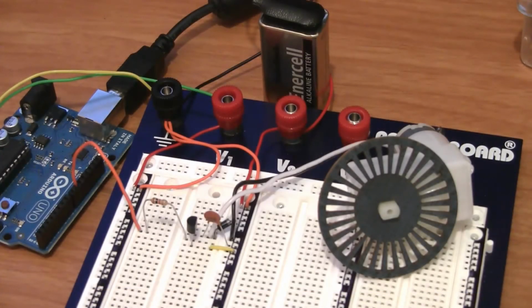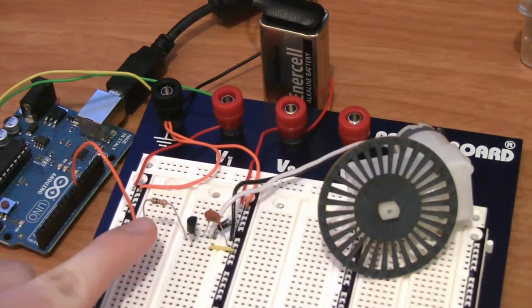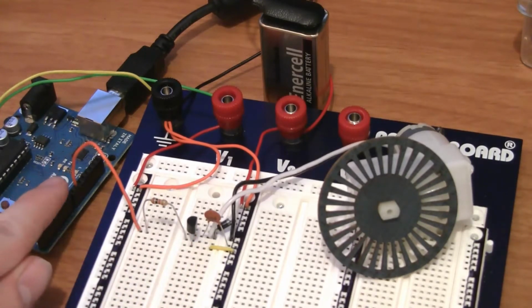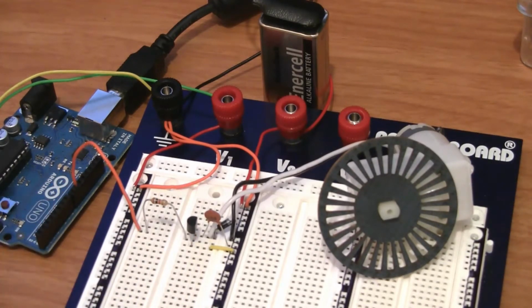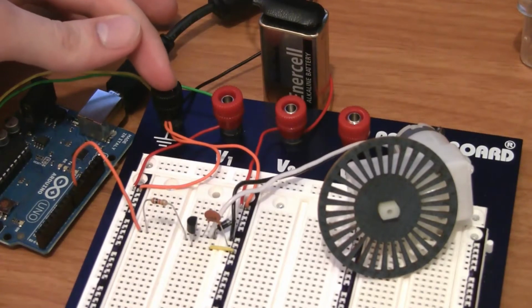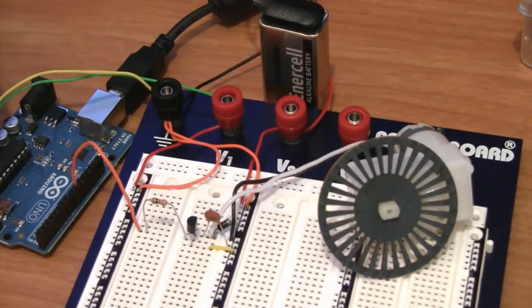Here's the circuit all wired up. Let's take note of a few important things. Here you can see the transistor, the capacitor, and the diode that I talked about earlier that will be controlling the motor. This is the 1K resistor that connects between the base of the transistor and pin 9 of the Arduino. The most important thing to note here, though, is that you always connect all the grounds between all of your voltages. I've used this binding post right here to connect the ground from the 9 volt battery to the ground from the 5 volt signal of the Arduino. This is to ensure that everything is operating off of the same reference level.